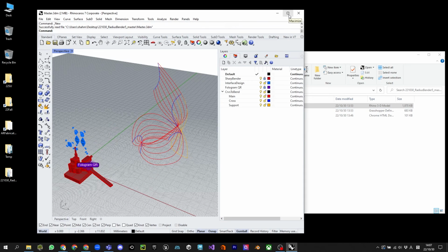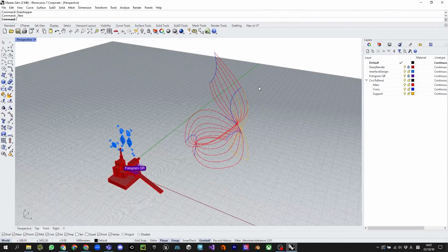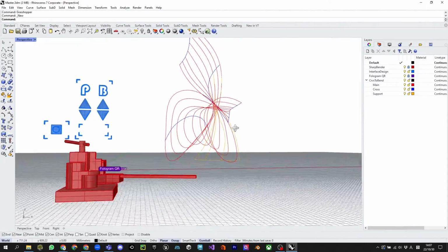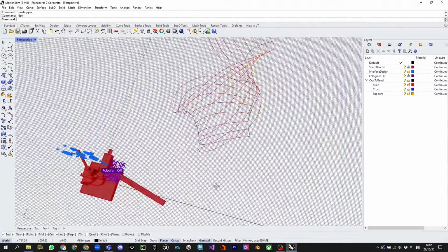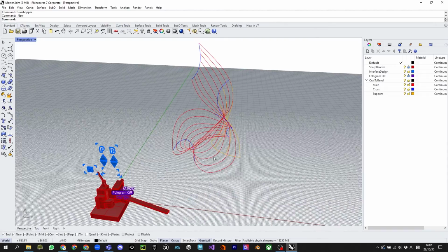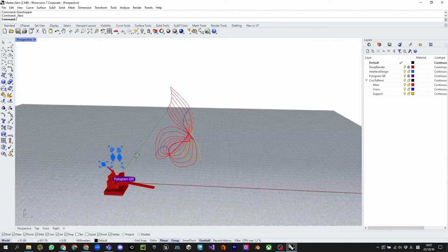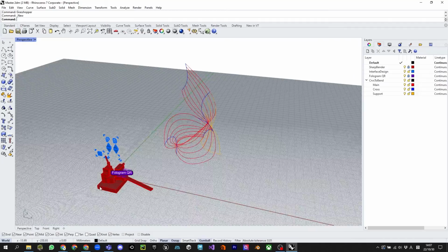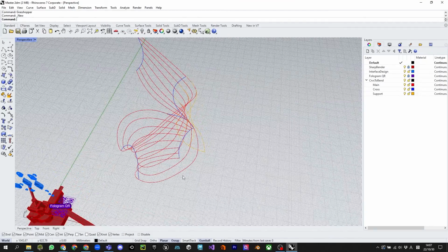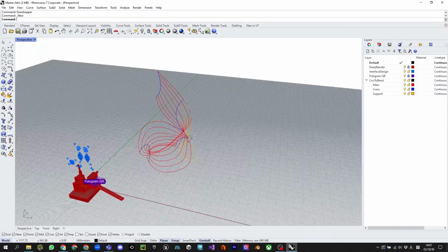This file is set up in millimeter, so if you have been working with different units, please make sure that your model is in millimeter before you bend it or use this file. And make sure that it's above the 000 position. So 000 will be basically where the table top is.